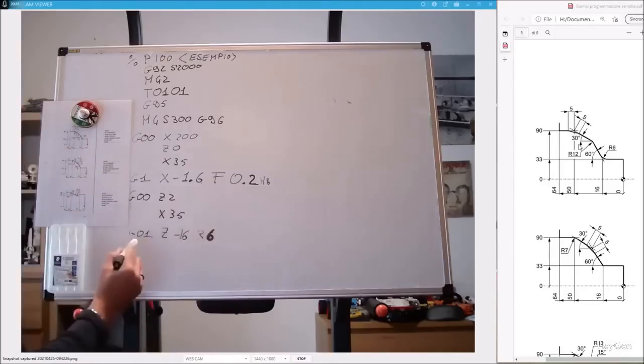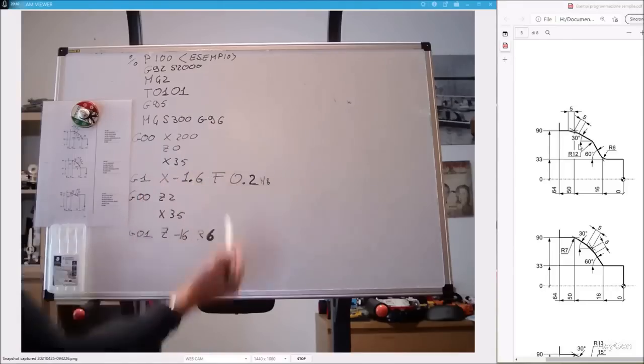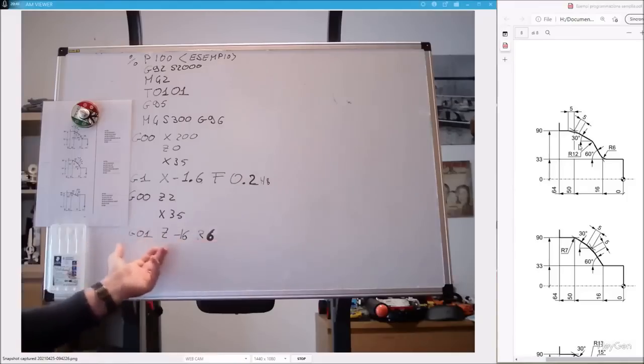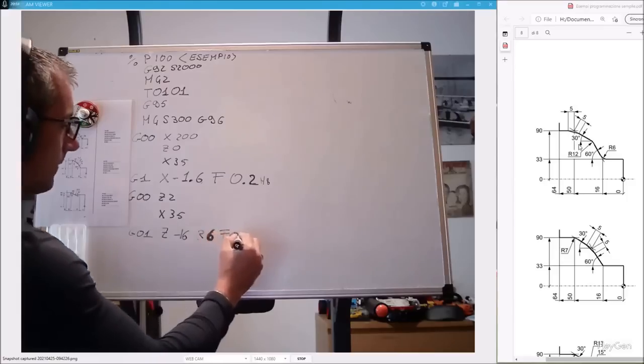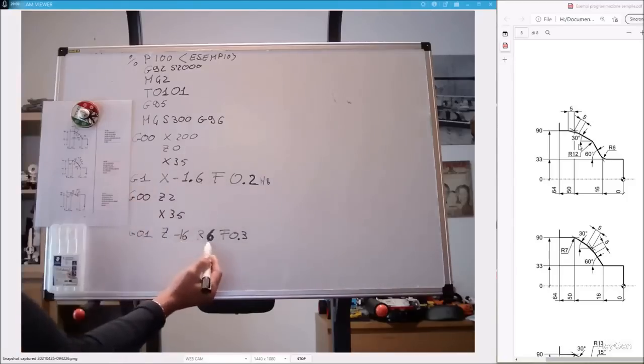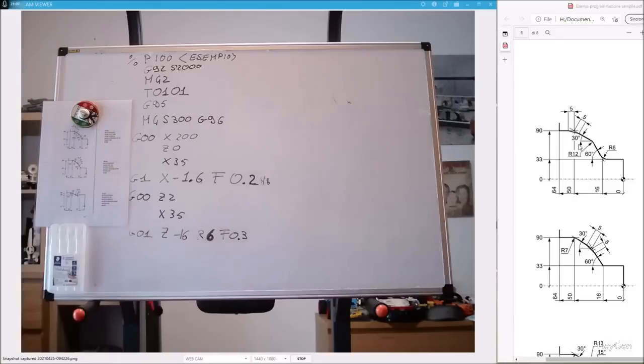Now, L1, G01, F02. If I do not modify it, the machine will remember the last programmed movement and feed, F02. Okay? If instead I want to modify it to F03, the only drawback of direct programming is that I cannot do the cylindrical part and the radius with a different feed unless I stop appropriately beforehand. So programming Z10 and then Z16 R6 with 2 different F values. Okay? In that case, I can do it.